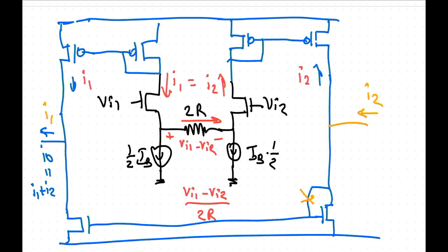Like I've come across these ones where the current you can sort of wrap around it as a single-ended. You have put in a cascode on top of the differential pair there. Yeah, that is very restricted in voltage swing. You can do that, but only if you're sure that the output voltage doesn't need to be smaller than the input voltage. Benefits to this then versus that? This is probably faster.